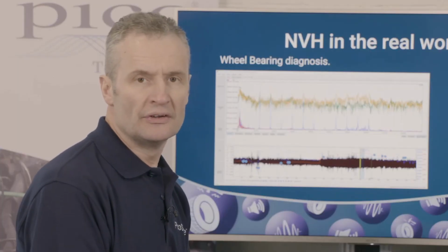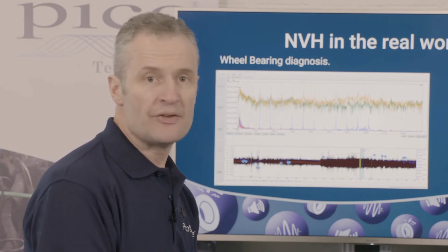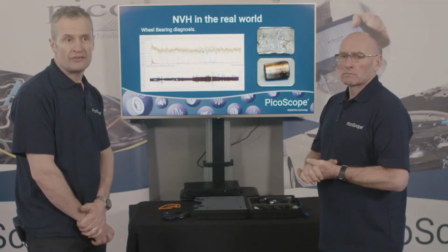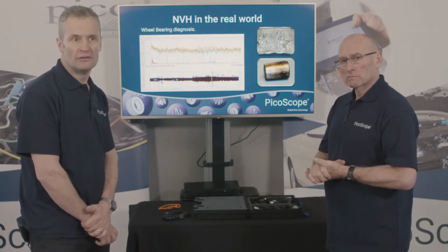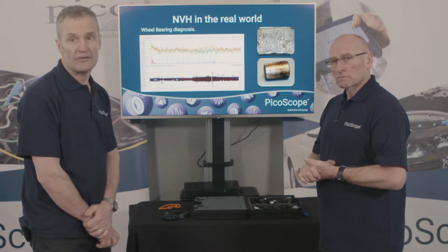Think about the damage to the bearing race, the number of rollers. Is the bearing rolling? Is the roller rolling? Is the roller skidding across the race? So to pull out just a single offending frequency from one failed bearing is near impossible.